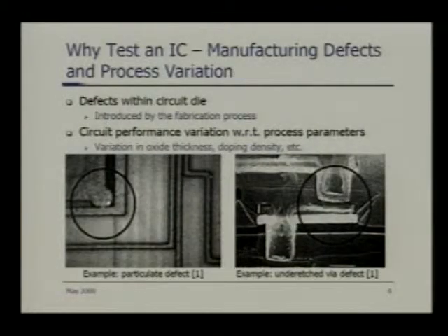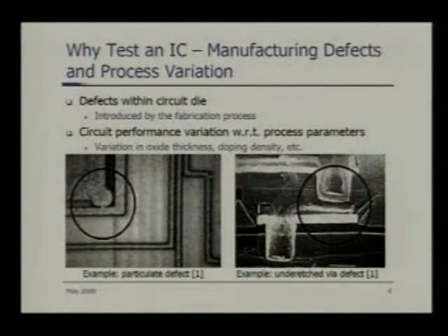So out of 2000 ICs, one IC has got this dirt particle, and somehow it is shorting this line and that line. In that case, you have got a short circuit problem, right? So this circuit is most likely not going to meet the specification because you have some circuit node shorted with some other node. Okay, so this circuit is not going to work. So although we made sure that characterization, I mean my overall device is passing the characterization, but this particular individual IC is not going to meet the specification, so we have to test for it.